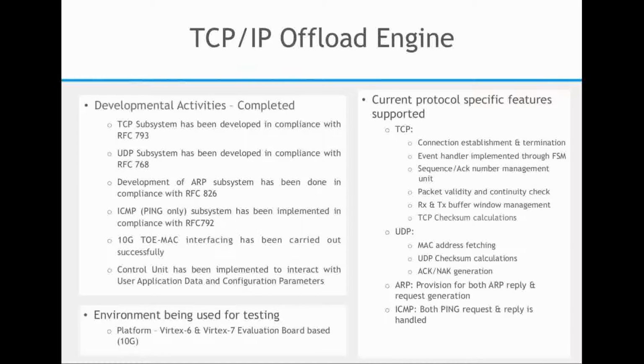As these MAC and DMA cores are not there with us, we have used node-lock MAC and DMA, which are time-limited to a few minutes, provided by a vendor to achieve 10G speeds. On the commercial off-the-shelf platform, we have been successful to handle 10G speeds for UDP and 4G speeds for TCP, where speed is possibly limited because of the node-lock MAC. Right now, as MAC and DMA at C-DAC Bangalore have come up, we have given a component of TCP/IP offload engine along with the support for integration, and it is expected that it will be completed in a short time.